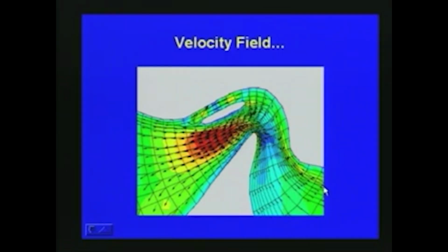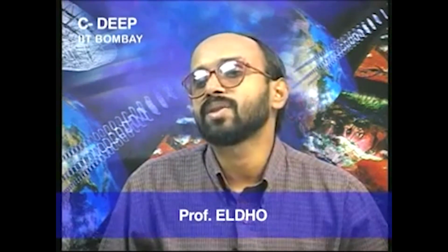Generally, to solve this kind of problem, we first solve for the hydrodynamics, that is, we determine the velocity, and then with respect to the velocity vector we describe the contaminant or plume movement. So it is very important that we know the velocity field, that means how the velocity is changing with respect to space and time. That is actually the major problem as far as fluid dynamics or fluid flow is concerned. The velocity determination with respect to space and time is very important.